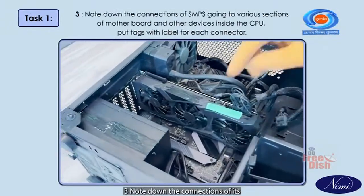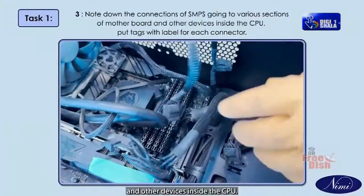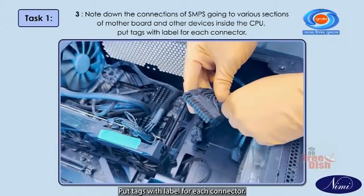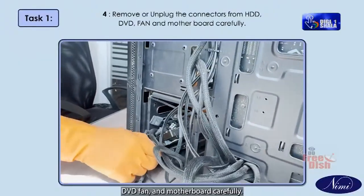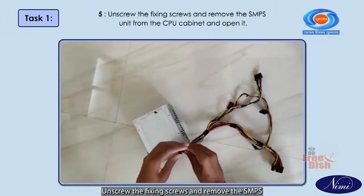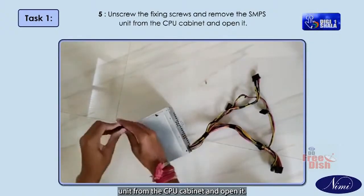3. Note down the connections of SMPS going to various sections of the motherboard and other devices inside the CPU. Put tags with a label for each connector. 4. Remove or unplug the connectors from HDD, DVD, fan and motherboard carefully. 5. Unscrew the fixing screws and remove the SMPS unit from the CPU cabinet and open it.